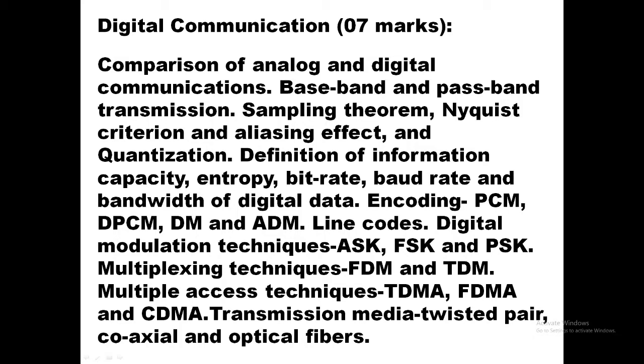Now in that, the syllabus shows that you should know what analog and digital communication systems are. You should know what baseband is, that is the basic information signal, and passband, that is when baseband modulates a carrier you get a passband. So you should know what baseband and passband are. You should know the sampling theorem, where the sampling frequency should be greater than or at least equal to twice the highest modulating frequency. Then on a similar basis you should know the Nyquist criteria and aliasing effect.